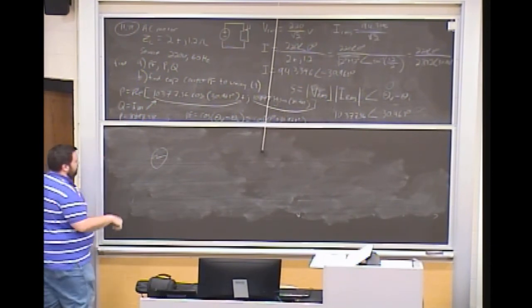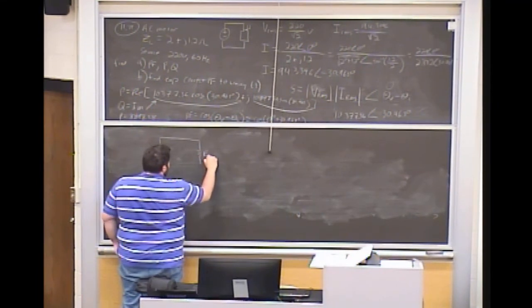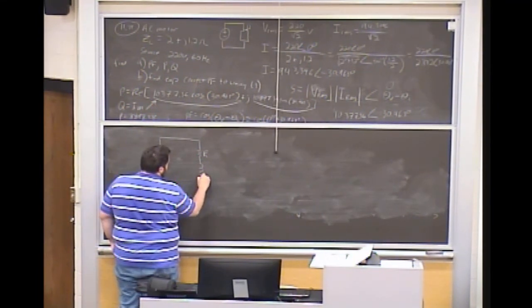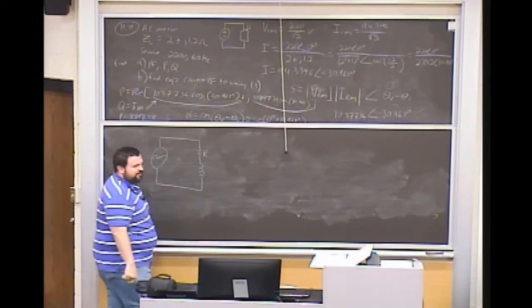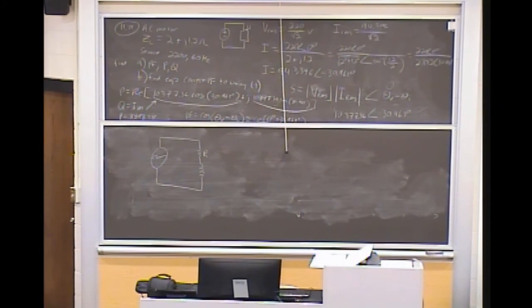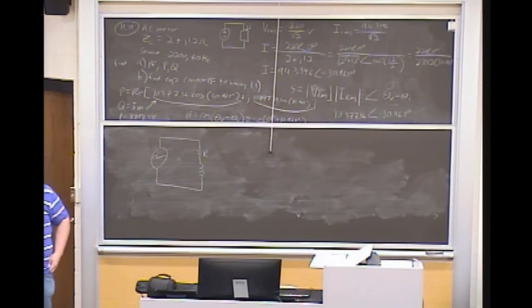If it's DC, we do a little plus minus. So you have this, and effectively right now, your load has some real part and some imaginary part, typically modeled as an inductance. Most loads, if you think across a broad power grid, will end up being inductive and resistive. Inductance largely comes because there's a lot of things that rely on motors. Think about your washing machines, your dryers, a lot of mixers, all those different things. There's a lot of inductors in what we're dealing with.